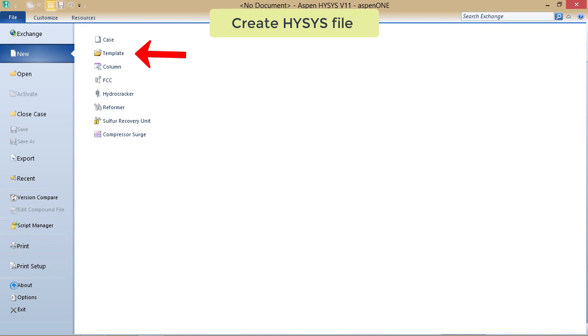The Template subcommand is used to save time by creating individual flowsheets of commonly used process units that you can install within other simulations. For example, if you are used to simulating a specific process unit like natural gas dehydration or a propane refrigeration loop, then you can create it as a case template and recall it anytime. Templates are fully defined flowsheets with a property package, components, unit operations, streams, and flowsheet specifications. And remember that you can convert the simulation case to a template.